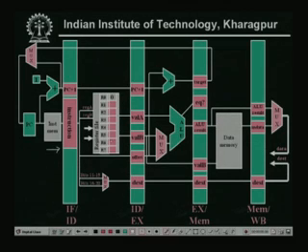Now, when one instruction has advanced one time step, that means the instruction is decoded. So, this is the first instruction, and now it has come here. Now, the second instruction is being fetched. So, when the first is being decoded, the second one is fetched. This is the overlapping region, and in this way it will proceed for other instructions also.